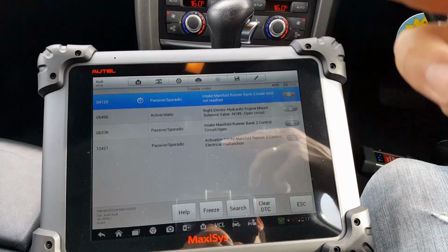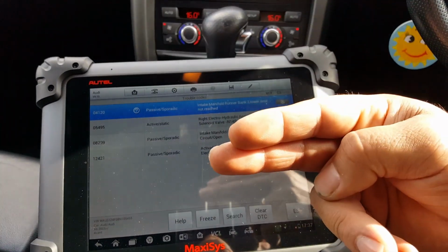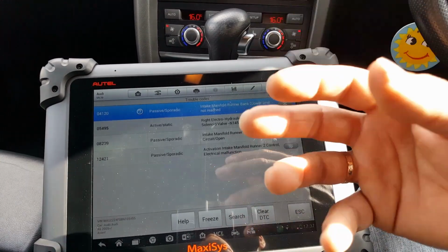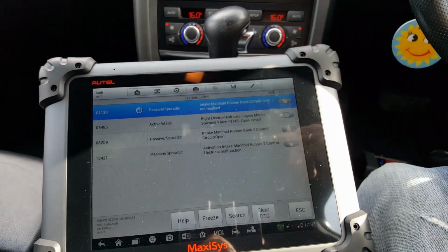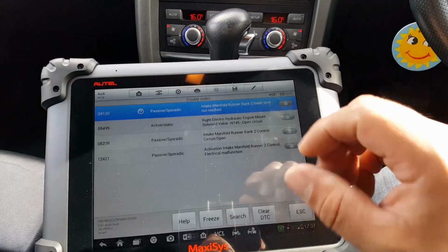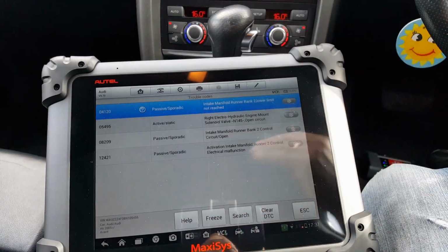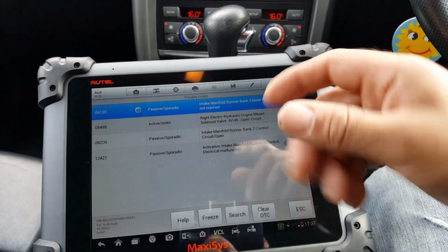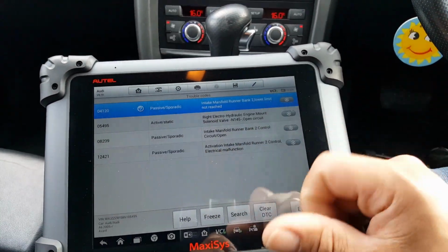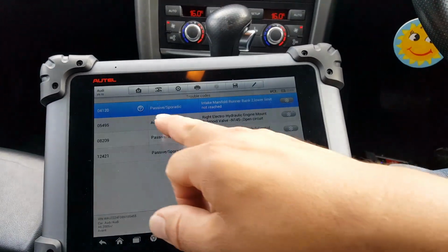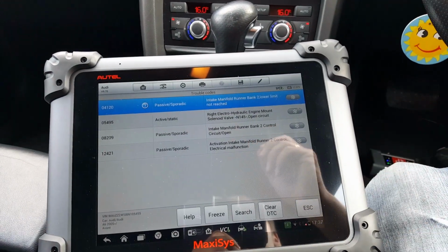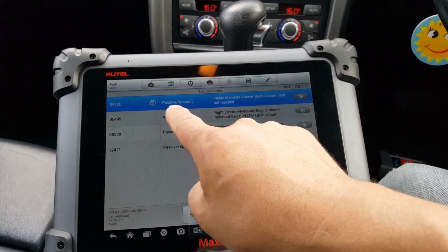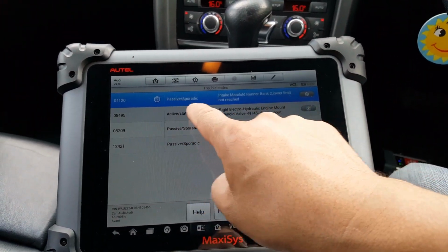So let's say it should stop at a certain place, but it's going over, and the ECU tries that 2 or 3 times, because it goes over all the time. It just says, hang on a minute, something's wrong here, and I'm not going to use this actuator. And it just leaves the actuator deactivated, and you can't move it freely. And obviously that will trigger the engine light, and the fault just goes like that. So what I'm going to do now, just to prove my theory, which I haven't done yet, the fault is now passive or sporadic.